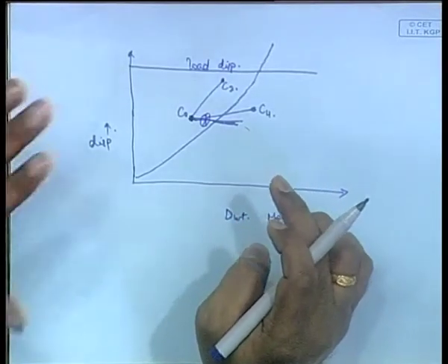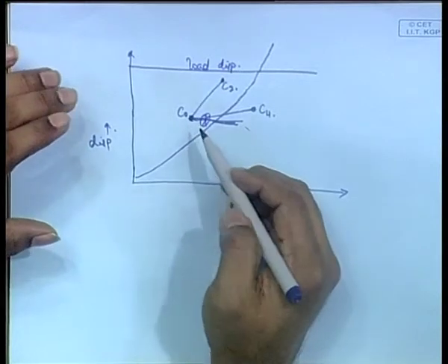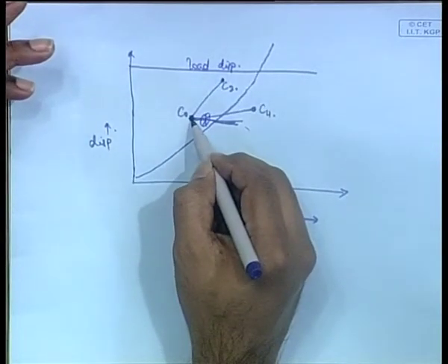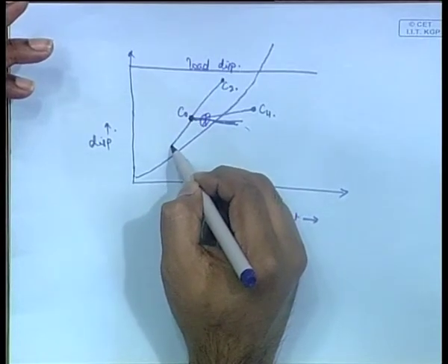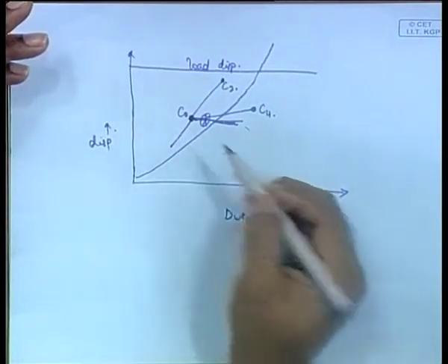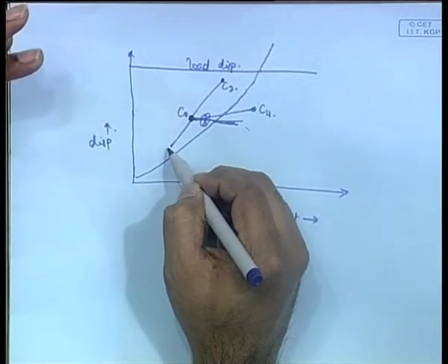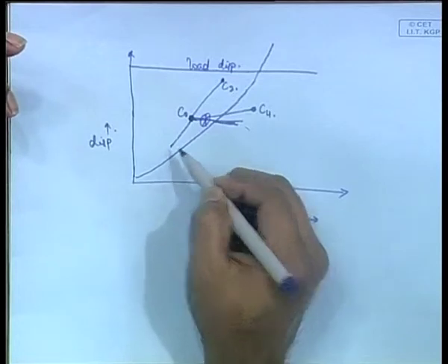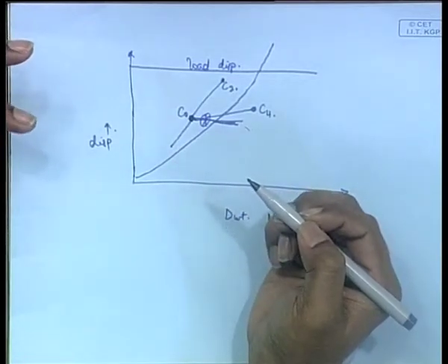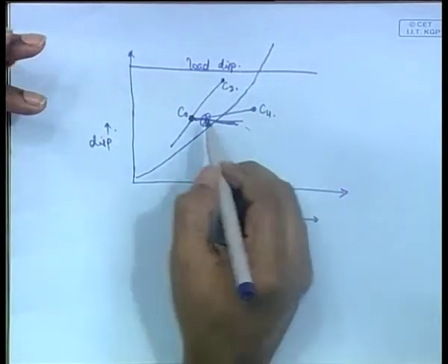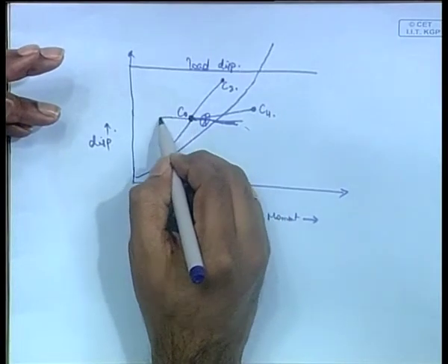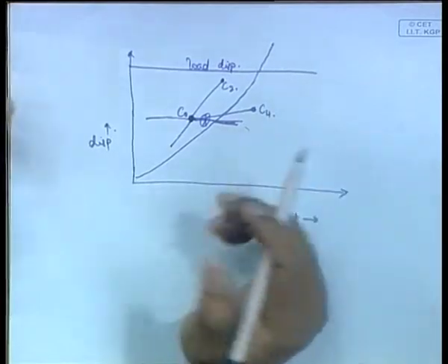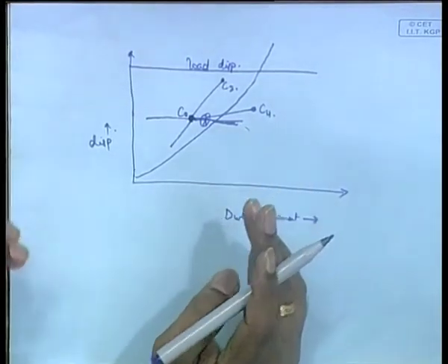Just to complete that, in case you are removing a weight, it will go down. Your dead weight moment is decreasing, and the displacement will also decrease because you are removing a weight. Similarly, you can change your dead weight moment the other way without changing the displacement, and the ship becomes more stable. So, these are different possibilities.